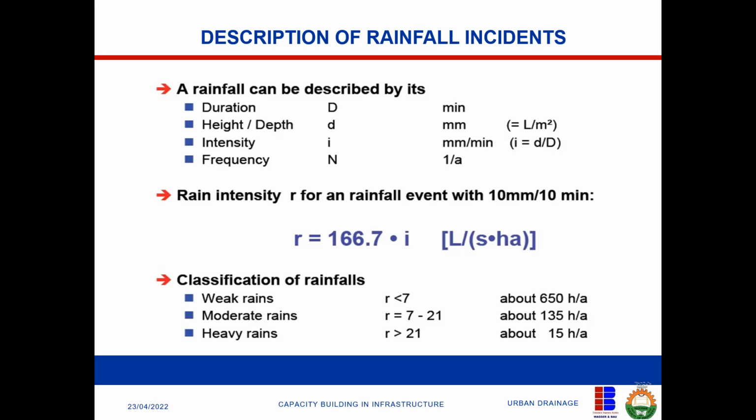When we say 5 years rain or 5 years return period rain, what we're trying to say is, what is that maximum rain, that highest rain that will fall within 5 years? What is the value of that? If I use that value to do my design, it means that in the next 5 years, if that storm should come, my design will sustain it. In some places, if you want to design something like a dam, they will ask you to study the last 10, 15 years or 20, 25 years, and find the maximum rain that has ever fallen in this place. That is the value you're going to use.